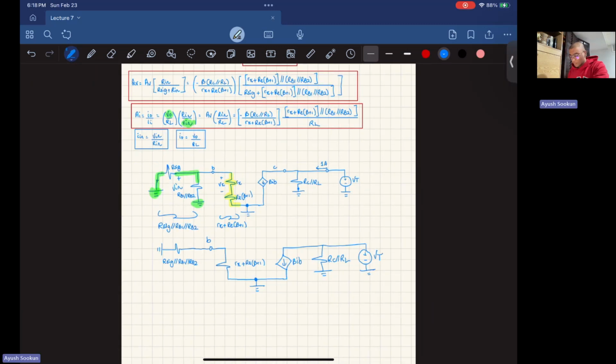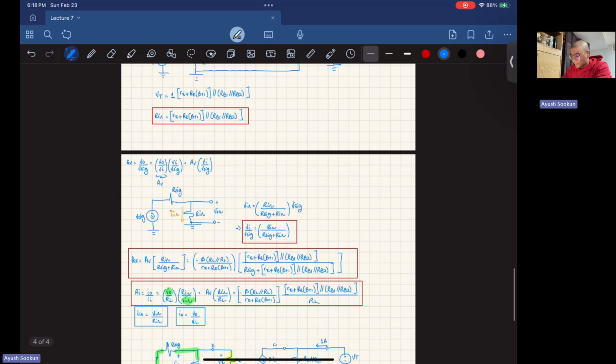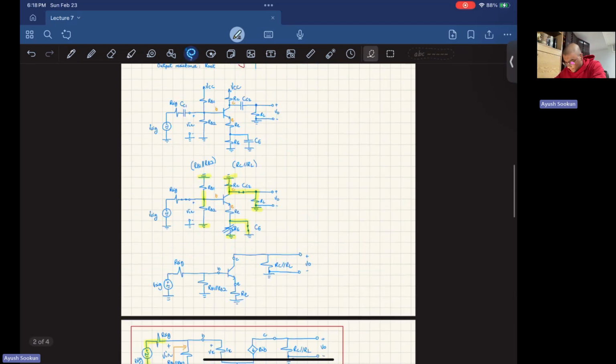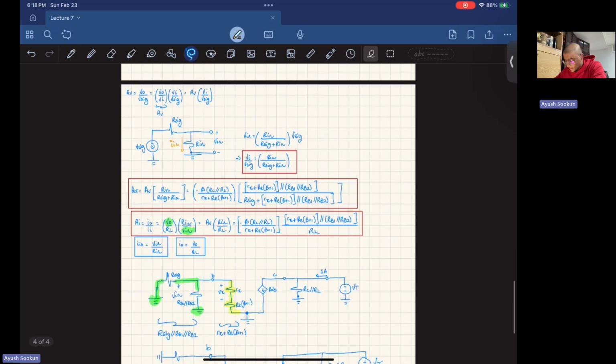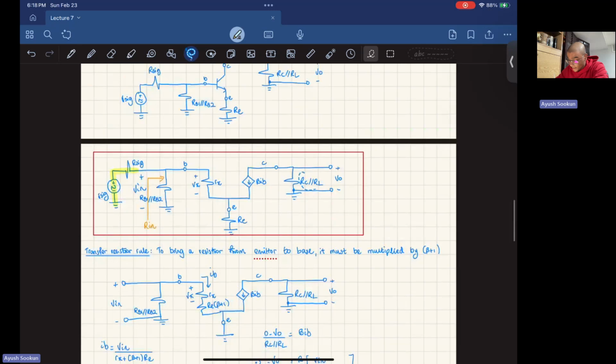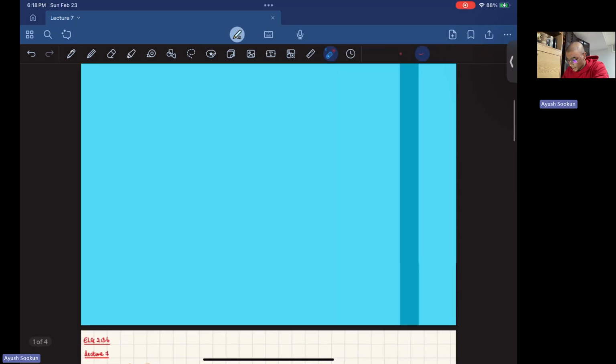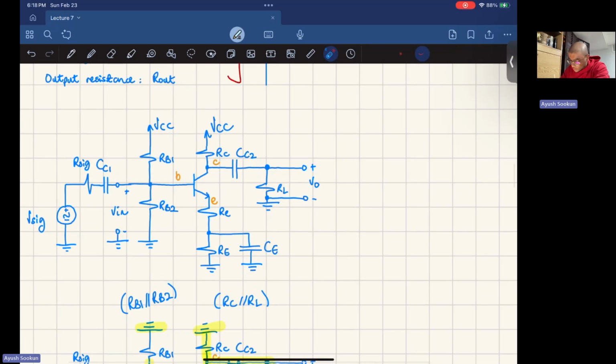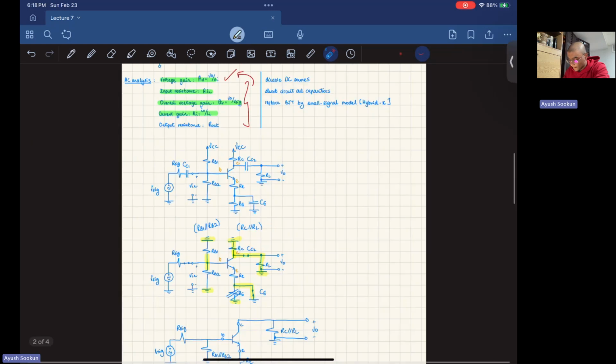By the way, one thing you have to keep in mind, because I'm copy pasting and I know my circuit, my electronics pretty well, is that here we did a combination, so you have to account for that. When I chose this circuit as my reference, this combination was already made. But if you look at the initial circuit, this combination was not made. So if you look over here, V out is only across RL. So when you're doing Thevenin, it's not parallel with RC, so you have to only have RL there, okay?